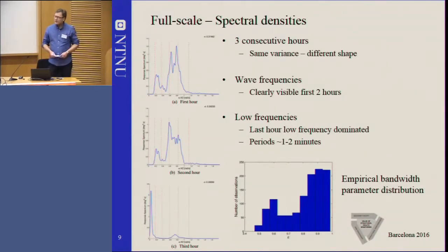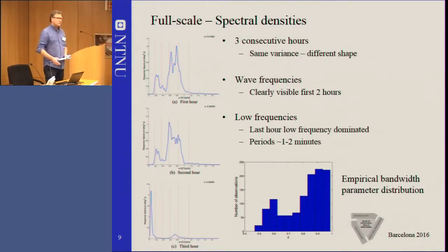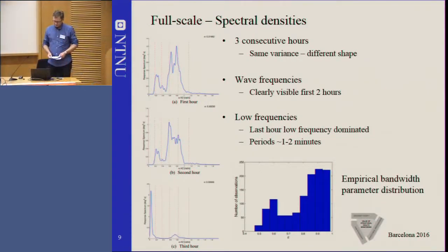So also spectral densities. There is some funny phenomenon. We can see we have 3 consecutive hours, and the first hour you have mainly response in the wave frequency regime, but then during the last third hour you have more slow drift motion, that is very low frequency motion, so you have some second order variation of the hydrodynamic loading on the vessel. That means you have frequency spectral change during these 3 hours, so you have to be aware that you have not constant frequency range for the excitation, and that also gives influence on the fatigue cycles.